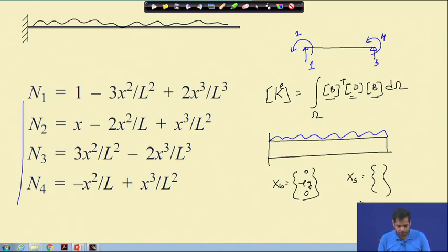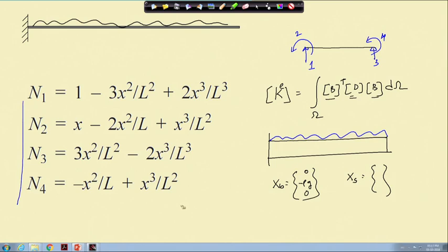Now, what we want to find out is, we know that at the element level, Ke into dE, where dE is the displacement, the degrees of freedom for a particular element, should be equal to Fe. Fe is the element load vector for that particular element. So, we have already seen how to express Ke. dE essentially are the unknowns, so we do not have to bother about that right now. We will now see how to express Fe.